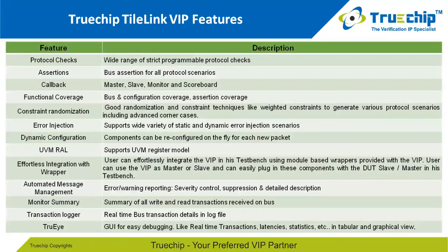The callback functionality is also supported in components like master, slave, monitor, and the scoreboard. The VIP provides bus and configuration coverage and also assertion coverage, and achieves 100% in all the simulators. The VIP supports the use of randomization and constraints to generate the corner scenarios.